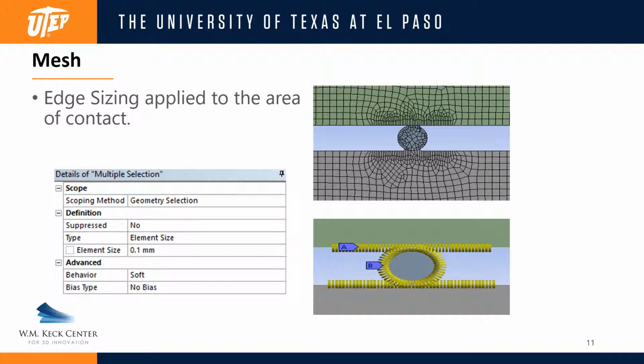And then for the contact areas, I used the edge sizing function, applied on the contact regions, which was made for more accuracy on each individual study.